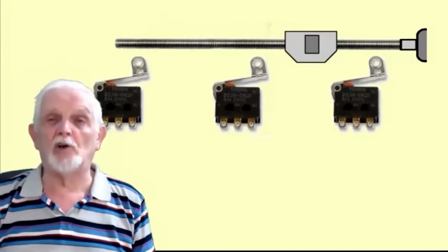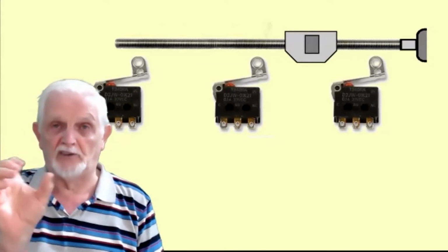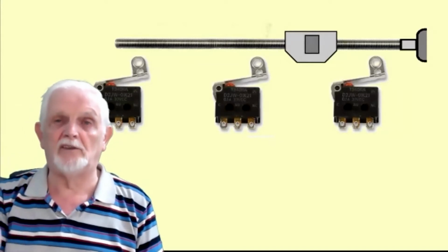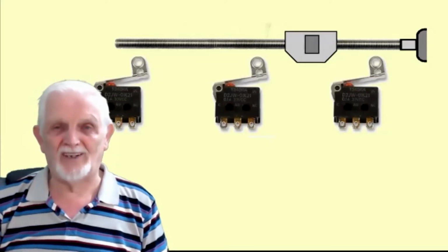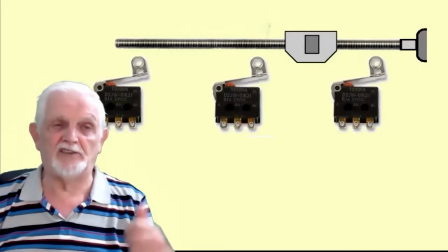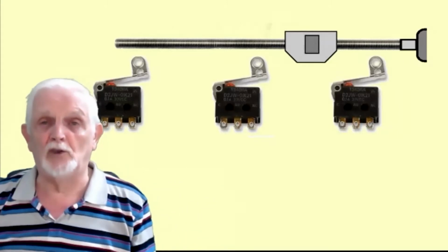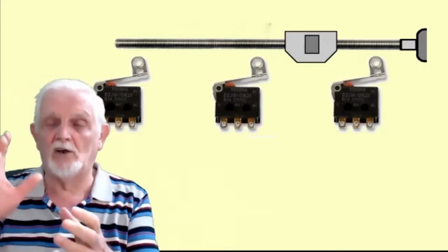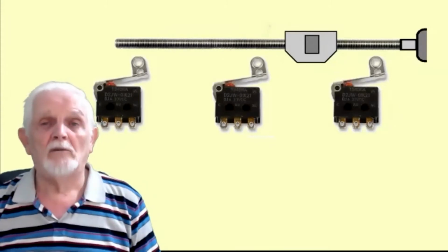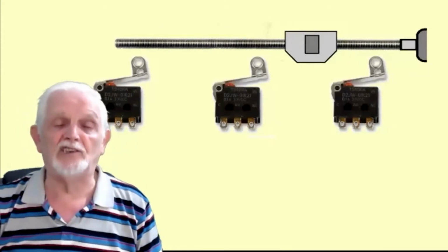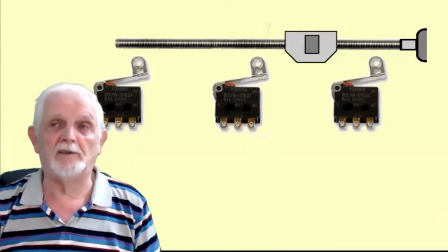On the threaded rod, the sled that's moving the barge itself also makes contact along the way with 3 micro switches. So it knows where it is at any point. It knows that when it gets to the far left end, you'll see that warehouse animation. It knows when it gets to the middle, it's going to bring a light on in another warehouse, and a lorry is going to reverse out, and so on. It's not train detection in this case, but it's used on our layout to detect positioning.